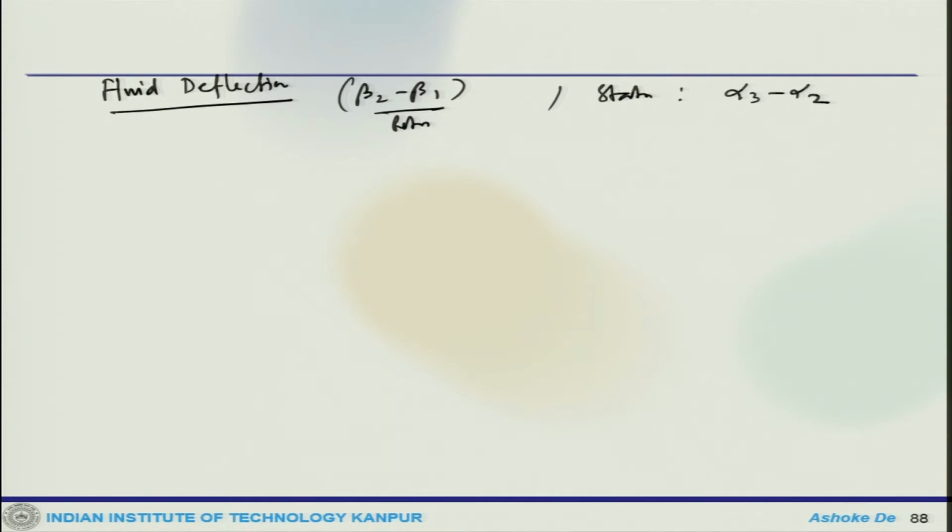Excessive deflection in the flow angle, which means a high rate of diffusion, will lead to blade stall. So, high deflection leads to stall. To maximize the specific work, the difference between the flow angles in the rotor must attain a maximum allowable value. So, if the inlet relative velocity maintains a constant angle beta 1, then the outlet velocity will control stall